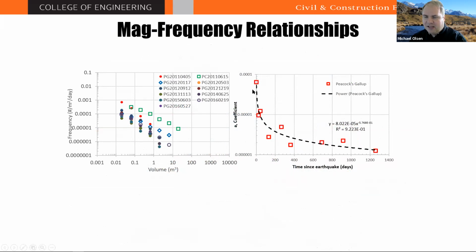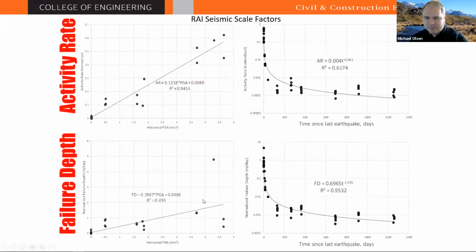So what this was telling them is that we need to be prepared after an earthquake for increased rockfall activity for some time after. The material's been really fractured and damaged, and so when you get storms through, the impacts on rockfall become much more severe.